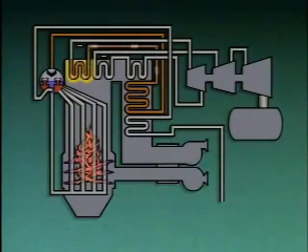The secondary superheater raises the temperature of the steam again. The secondary superheater is usually located closer to the boiler furnace so that it's exposed to higher temperatures. The secondary superheater may be either a convection superheater or, as in this case, a radiant superheater. This boiler has an attemperator, or desuperheater, located between the primary and secondary superheaters.